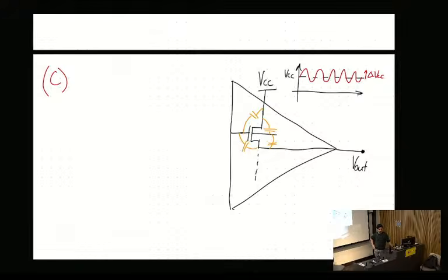Yep. Yes, yes. So good question. The answer to that is it's probably the bane of every microelectronics engineer's existence: parasitic capacitance. Honestly, a lot of the problems we face in microelectronics are because of parasitic capacitance. It literally stops us from doing a lot of the things we want to do. But as something interesting, dynamic RAM is actually based off of parasitic capacitance. We use the parasitic capacitance to build RAM. So just as an example.